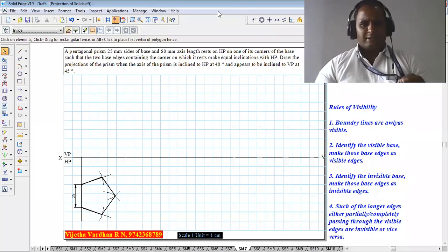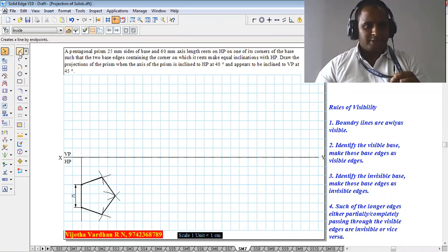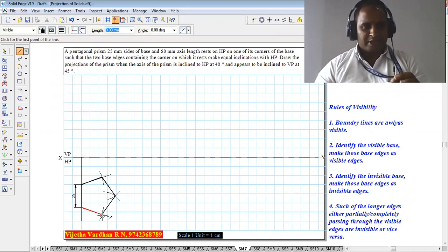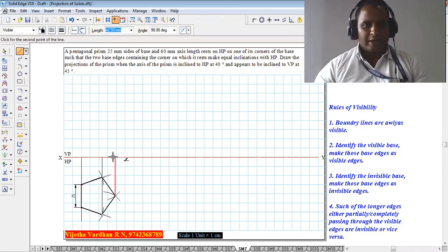Now, once the pentagon points have been obtained, using HB pencils, darken the pentagon properly. And afterwards, taking a pencil and a scale, one has to draw the projector from the respective corners till it touches the XY line. And afterwards, we have to construct any 2 perpendicular bisectors like this to get the intersection point, which I am going to show you now.